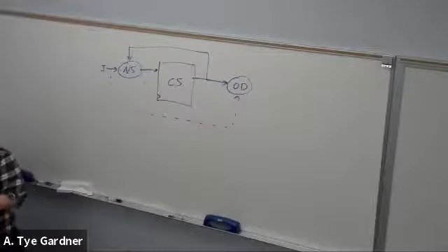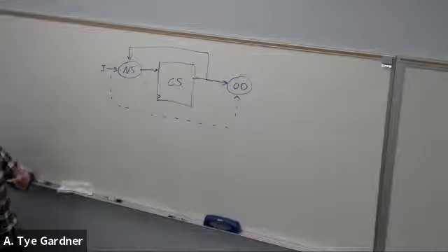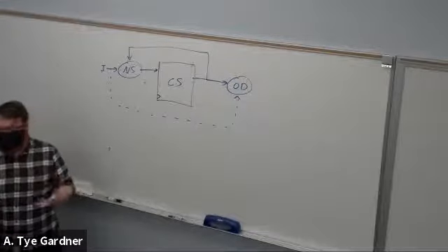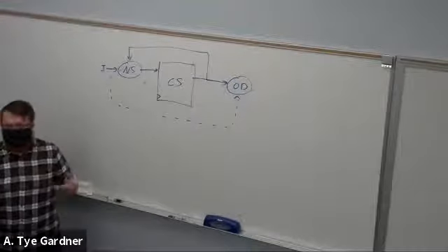All right. So we started with that lab. I kind of directed you through the easiest way to make a state machine in VHDL. Let's go with a bit of a harder one that deconstructs into all three parts. Let's use all three different parts, and we'll start with the next state decoder, right? The next state decoder is going to be in a process, and again, it's combinational logic.